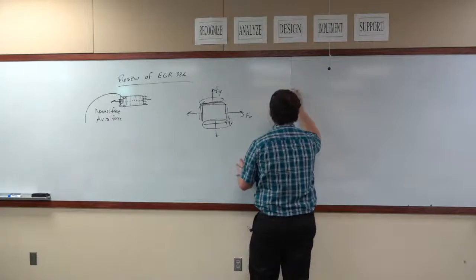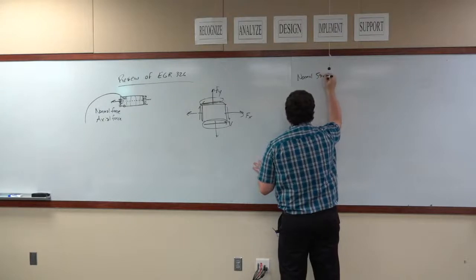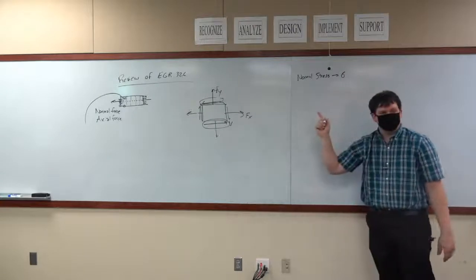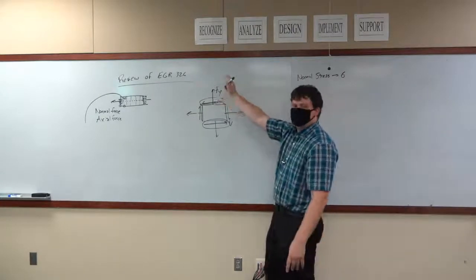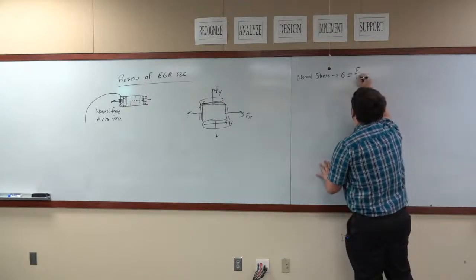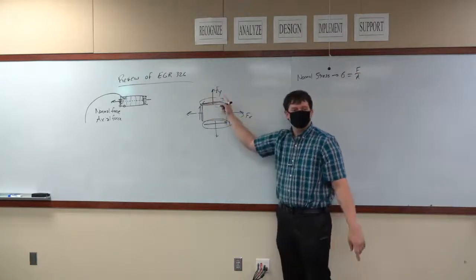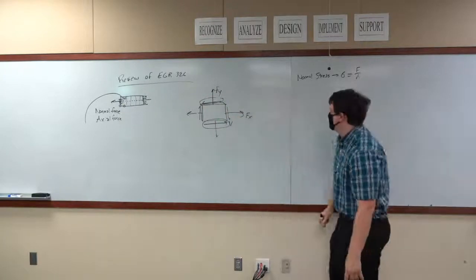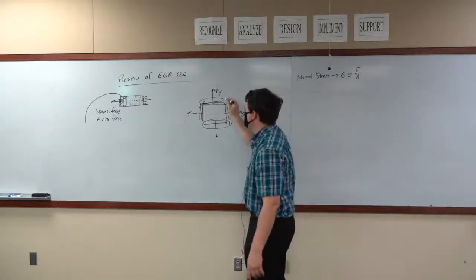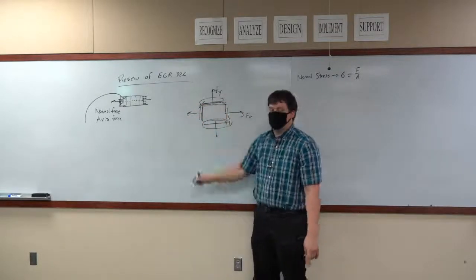Type 1 is the normal stress. Normal stress is given by the equation sigma. Sigma indicates that it's a normal stress. It's pointing into the surface. Sigma is equal to F over A, where force is how much force over how much area that force is being exerted over. So here, if we wanted to figure out sigma for this force, it would be how much area that force is being exerted over. It would be the area of the top of that box.